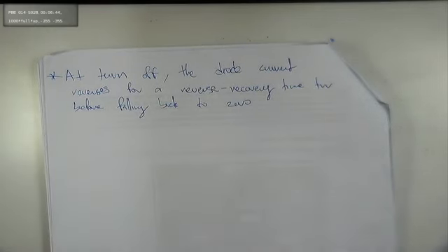So this means that the diode requires a negative current to sweep out the excess carriers to bring it back to 0. So remember this, the diode does not come back to 0 immediately, it requires a reverse recovery time to come back to 0. This is the point that you should remember always.